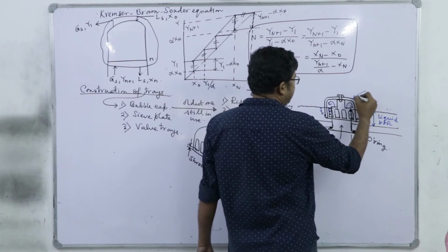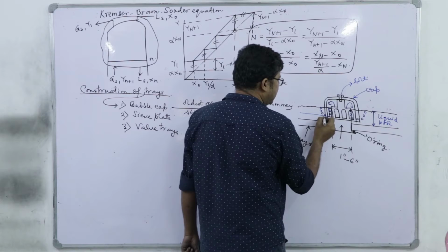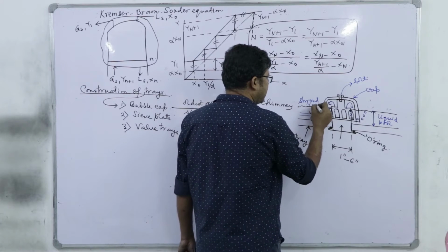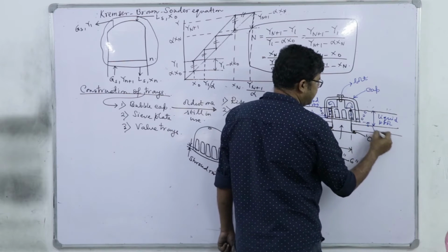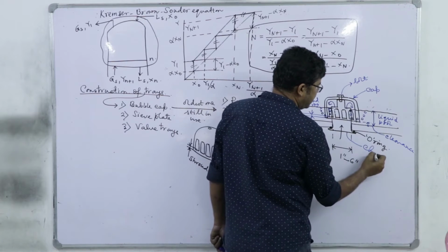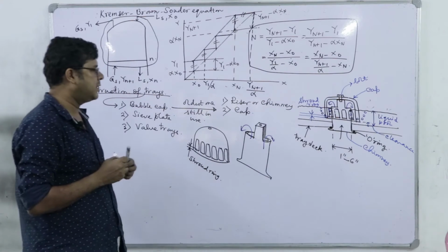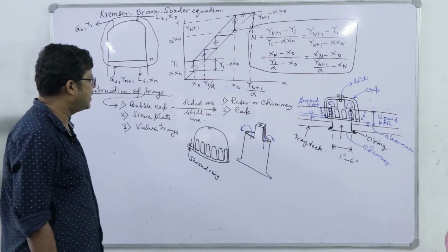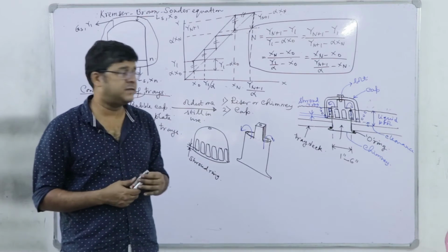So that's the cap, bolt, this is the shroud ring, this is the deck, this is the clearance we have to maintain, this is the chimney, and that's the tray deck. So this is overall the bubble cap arrangement, and there are different variations in design, but this is the basic one with which we can go for a very efficient mass exchange.